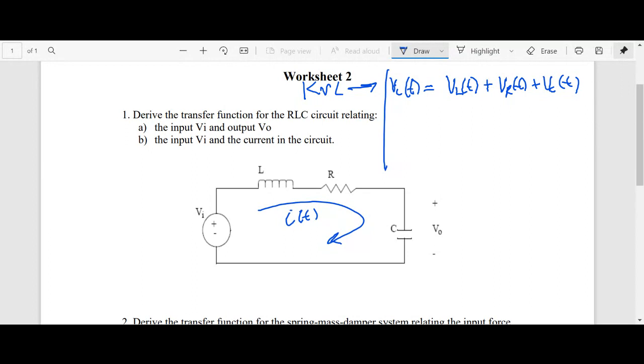According to what was just said, which is absolutely correct, we need to have 2 variables in the expression for us to proceed with deriving the transfer function. What 2 variables are these? VC or VO and VI. That's correct. So what we want is VO of S over VI of S. Whatever it is equal to is going to be our transfer function. That's what we don't know. We want to find that. So we're interested in keeping VO, and this is supposed to be VI.